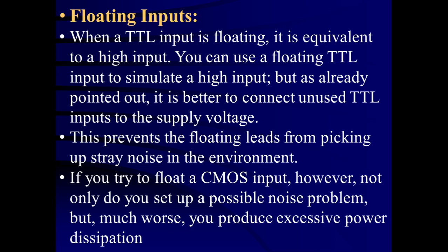Here also we have to connect the unused input to the supply voltage to prevent any stray noise in the environment. In case of the TTL, it only picks up the noise signal, and because of that the output may be changed by the unwanted signal; that noise signal can falsely trigger the output signals, and that's why it should be connected to the supply voltage.